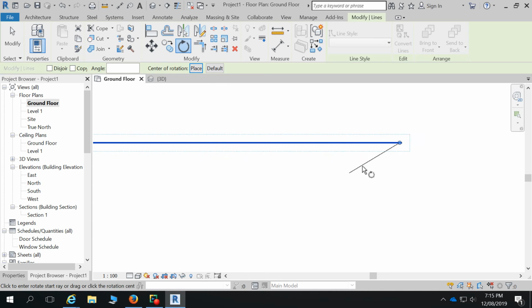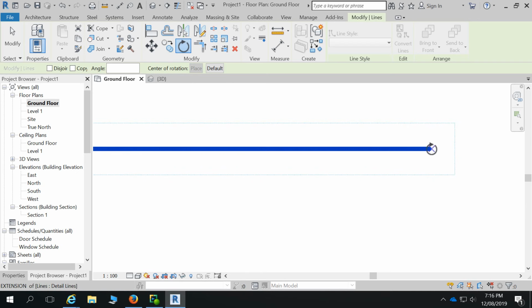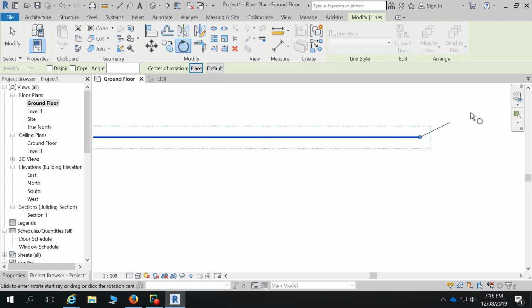Now the next thing that you'll see is that I've placed it towards the end of this line, and I'll put it right on the end actually. Let me just use the place button, it's a bit more accurate. Grab the end point snap. The next thing is like a lever. So this little bit that's off, it's like a little lever, or maybe a crowbar if you imagine it like that. So we're going to put it in at one position and then use it to lever around that axis at a certain angle.